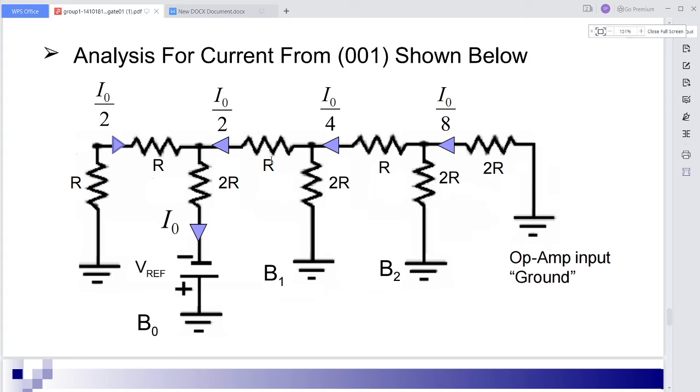Then in the series this is R, now 2R, now this is 2R. Now here we got the 2R and R, 2R and R. Now here we got the 2R, here we got the 2R, and here we got the R. By simplifying that one, you can get the R equivalent in this circuit, which is about 2 by 3 R.